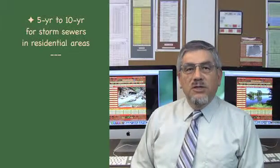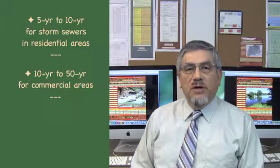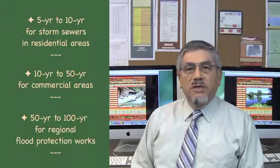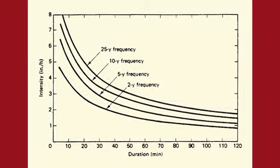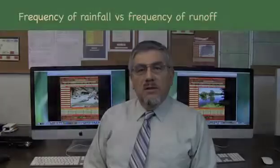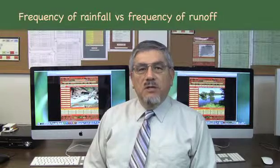A rainfall frequency is chosen to vary from 5 to 10 years for storm sewers in residential areas, 10 to 50 years for commercial areas, and 50 to 100 years for regional flood protection works. Rainfall intensities are higher for shorter durations. Rainfall intensities are higher for longer frequencies. The frequency of rainfall and runoff events may not be the same. In practice, runoff coefficients are adjusted upward to reflect postulated decreases in runoff frequency.